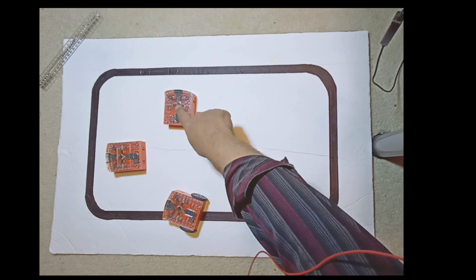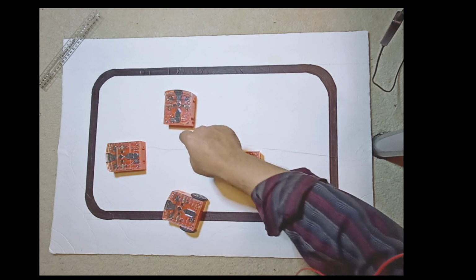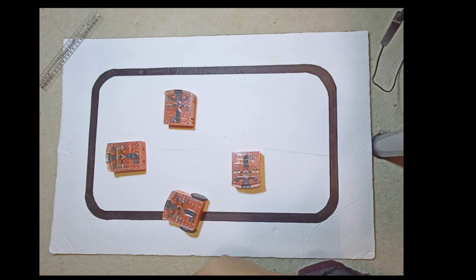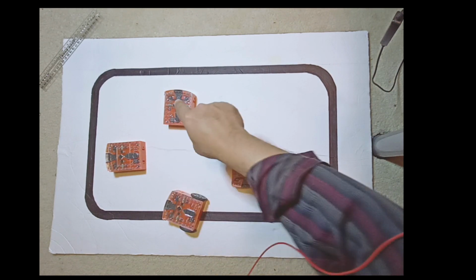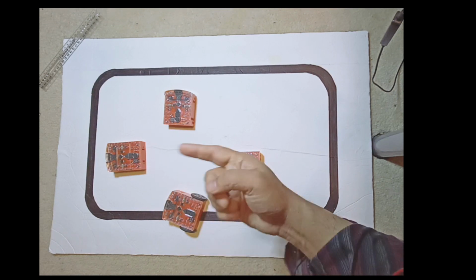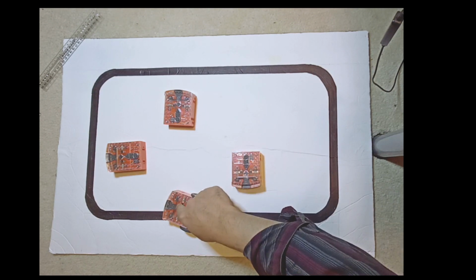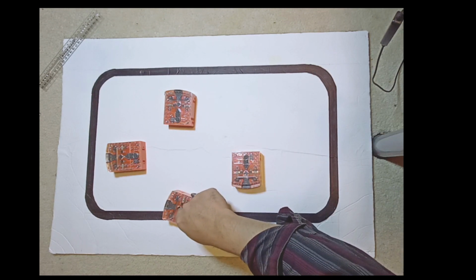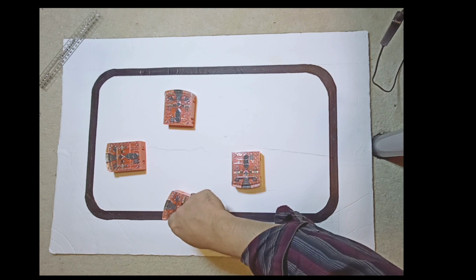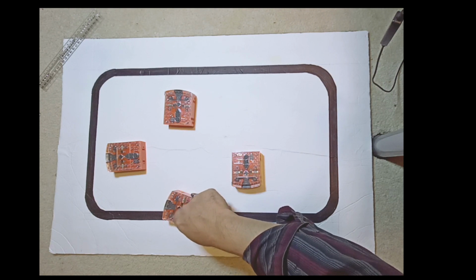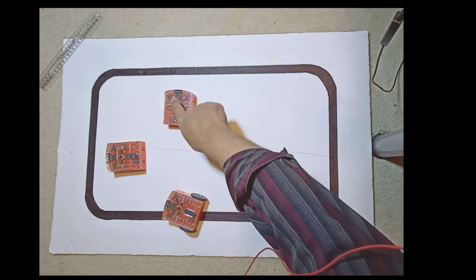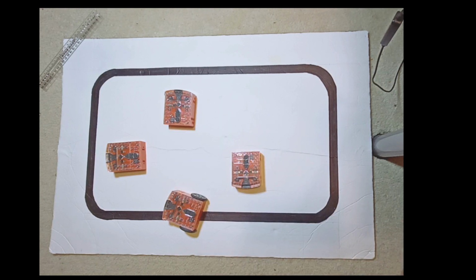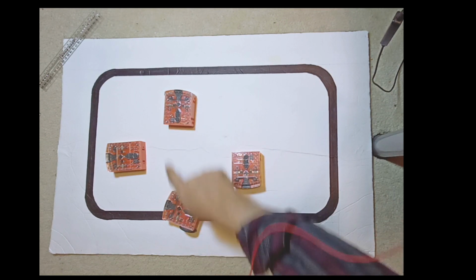When it reaches the train station, the station will use the collision detection to detect that the Edison robot has arrived, and it will send a second infrared signal to the train Edison robot that it needs to cancel that status and stop tracking the black line for that specific station, and the train will stop over there.